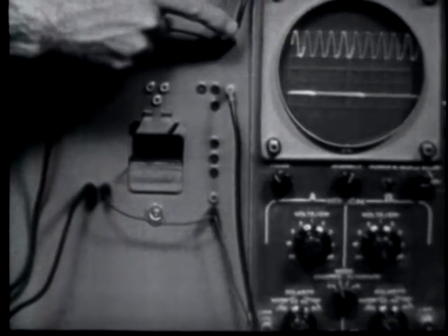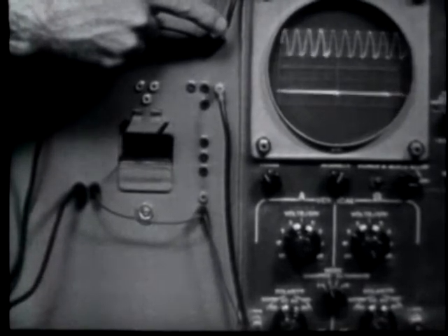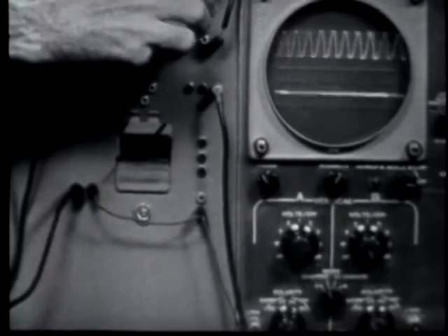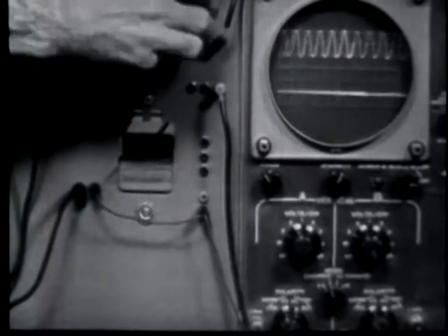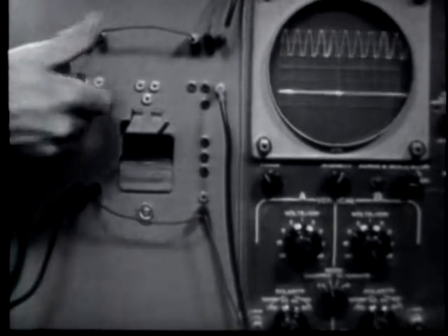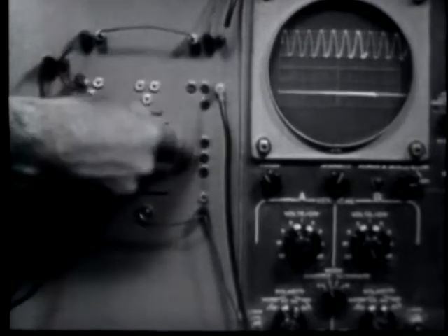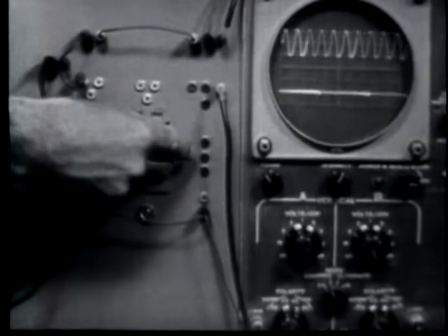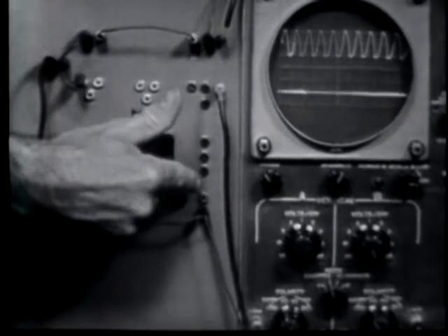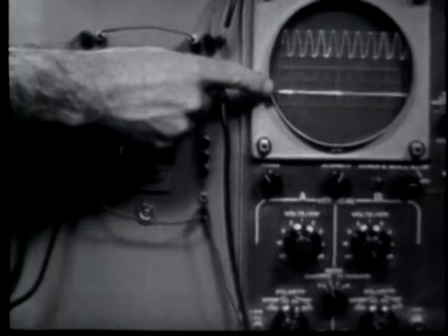Now, this is the frequency directly from the trainer or from the signal generator, the top trace of the scope. The other lead here, the one in the middle, is used to provide a synchronization voltage or an external trigger for the sweep circuits of the oscilloscope. Now, down here, in this circuit here, is where we'll hook up our filter components. This is the series position, and here is the shunt position. Now, notice, as is always the case, the output is taken across the shunt component and is displayed on the B trace or the lower trace of the oscilloscope.